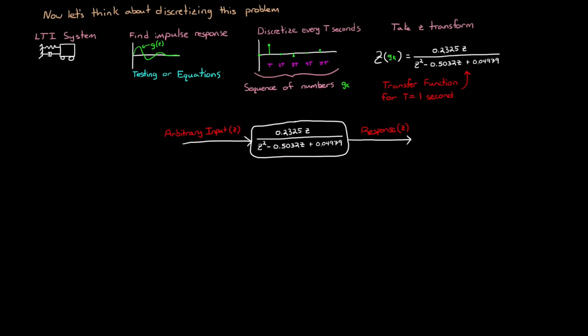If the system we just converted was a controller we designed, then we can think of the input as a sequence of discrete set points, maybe a set of desired motor speeds, and the output would be a discrete actuator command, like a new voltage command to get to that motor speed at every sample time.